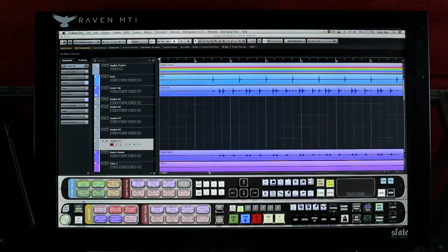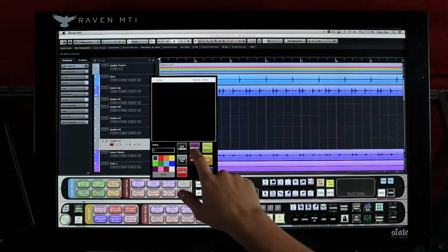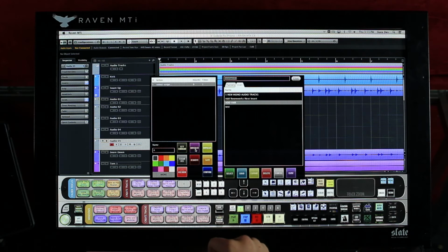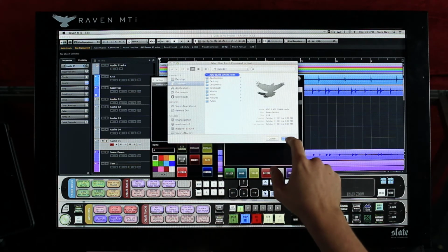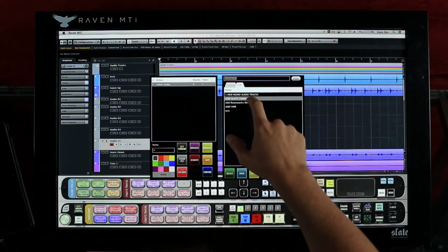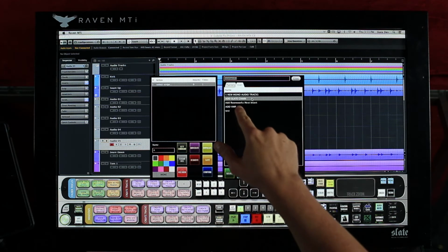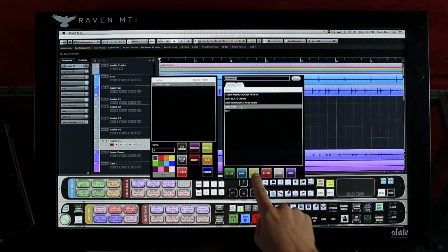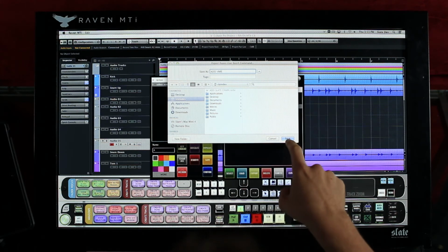Importing a batch command is simple. In the Batch Command System menu, hit Quicklist and select the User tab from the top. Now, hit the Load button and locate the .ravbc file on your computer. Select the file, and Raven will import the file into the User tab. Exporting is similar. From your User tab, select one of your saved batch commands and hit Export. This will save the file to your desired location and can now be shared with other Raven users.